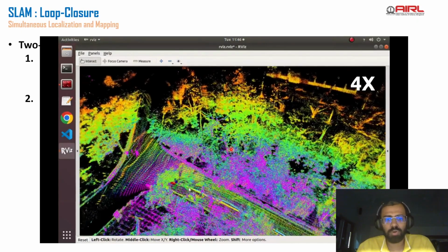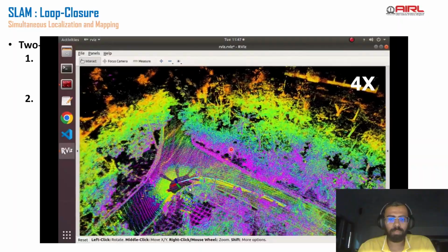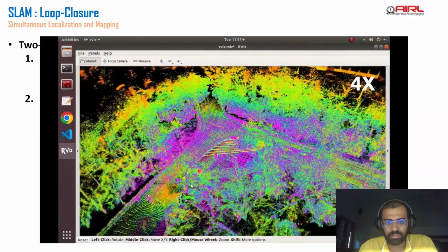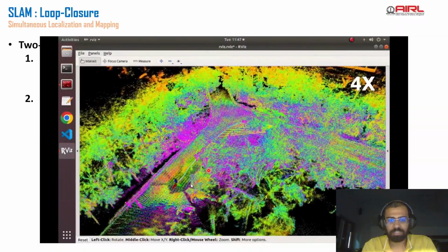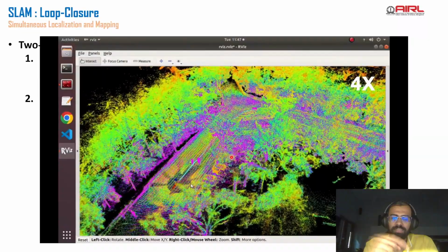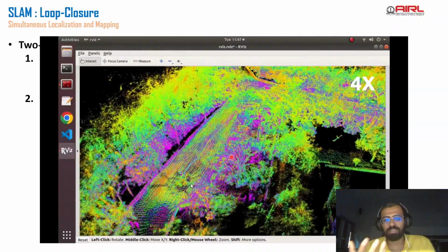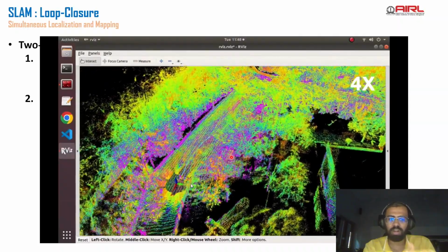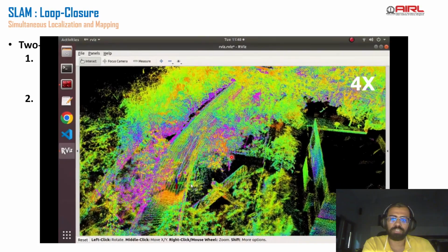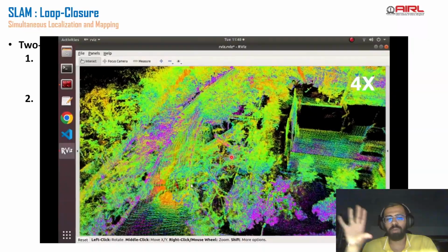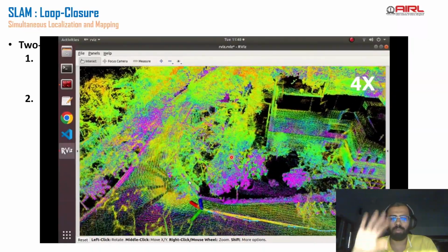So this is what it would look like. You can observe that there are these yellow lines, right? I hope it is visible. These yellow lines are the factor graph or the loop closure stuff which is happening, because it's a 3D LiDAR, even if it's a bit away from that particular same location, especially on corners, you'll still be able to see a good part of common space.